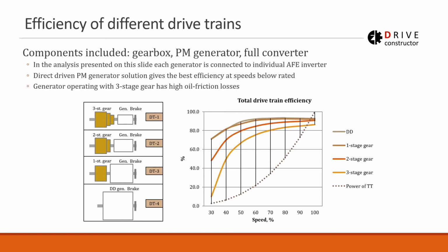So this is one thing to remember. Second thing to remember is that efficiency at the full load and at partial loads, they differ. So efficiency is falling with the falling load on the gearbox. And the same is actually usually more or less true for an electric machine.